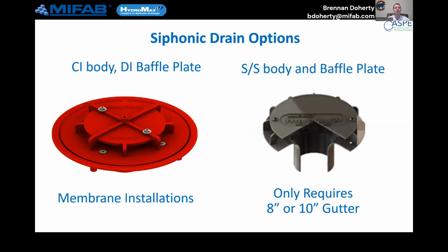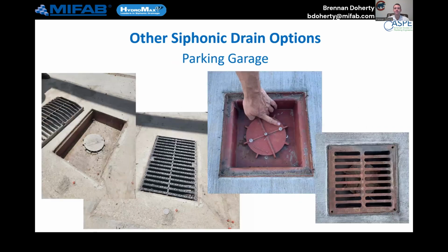As far as the drains go, at their base, there's really only two models. On your left, you have your typical TPO membrane roof. Membrane goes in there, clamps down. On your right, you have your stainless steel spun drain. We use this in gutter style applications and parking sumps. If you have a stadium build with a sheet metal roof, use something like that. We'll go over some advantages and why.